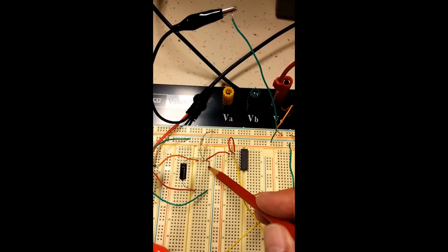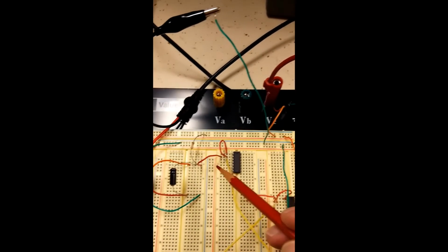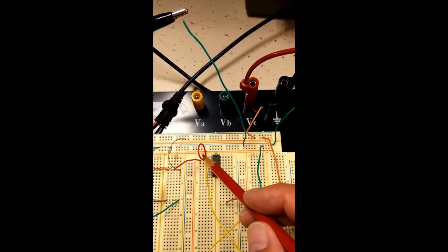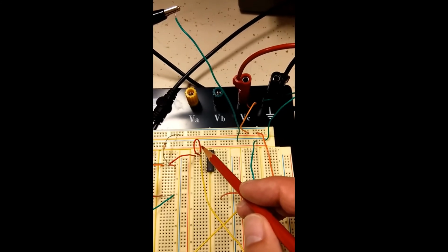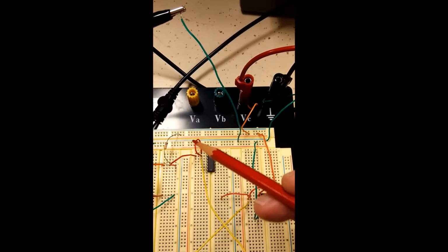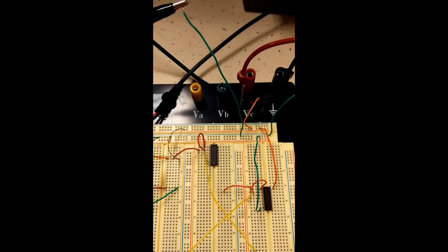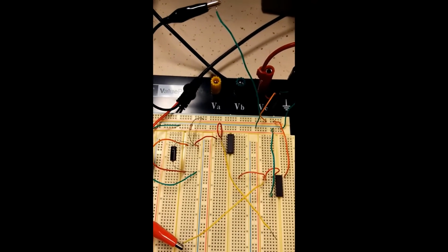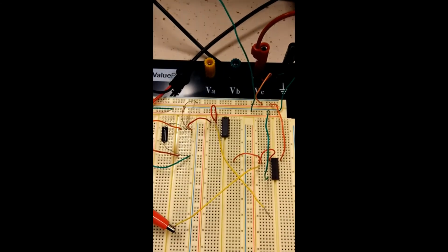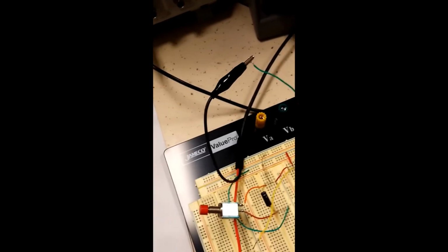So the input for the circuit here is 5 volts, a high signal, or 1, for A and B. So you have input A, input B, and the output should be 0, because it's a NAND gate: 1 and 1 gives 0 output. All right, we have to check. We use this output from the 4093.